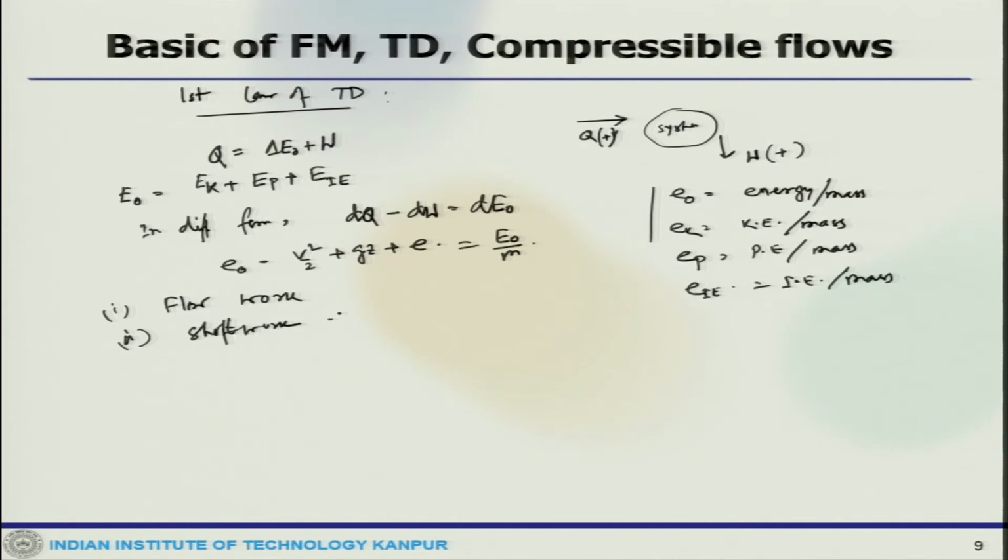So, the soft work is any other form of work, for example, work transferred through the control surface by shaft, electric current, etc. Now, similarly, if we use the RTT, we write dE0/dt would be ∂/∂t of the control volume ρE0 dV plus the control surface ρE0 V·dA.